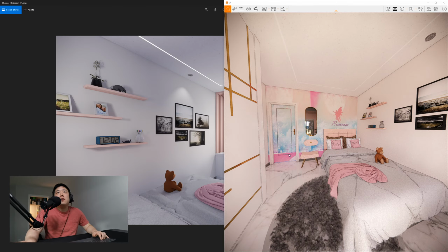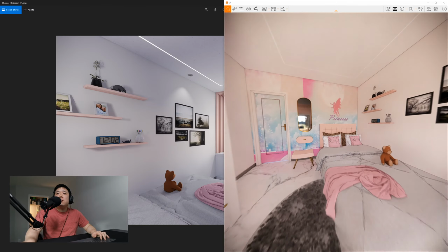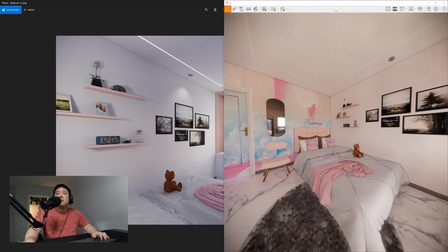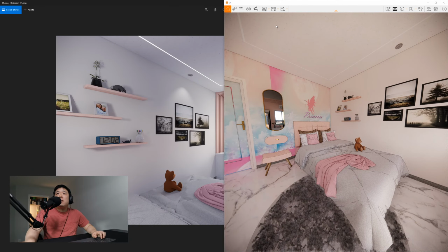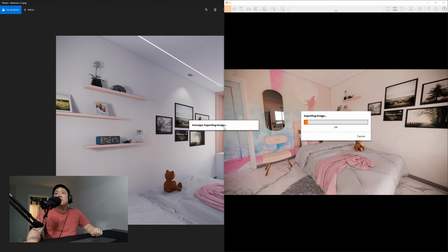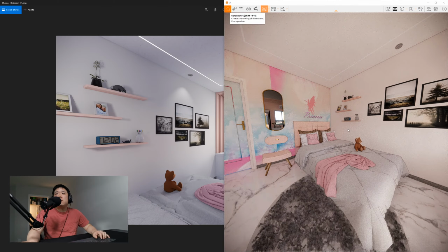And then just to save renderings, we would position ourselves. As I've said, I would look at it like so, and then either click on this here or Shift F11, and then it's going to export a snapshot or image rendering, if you would.